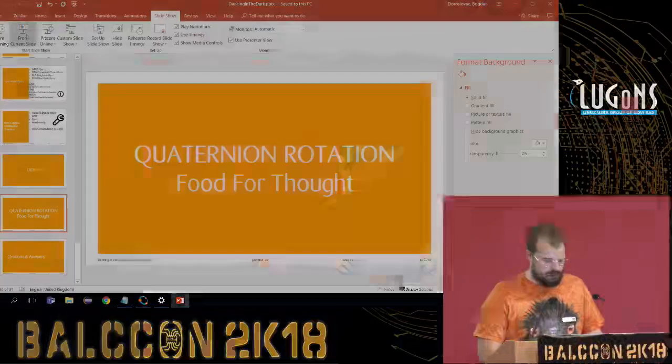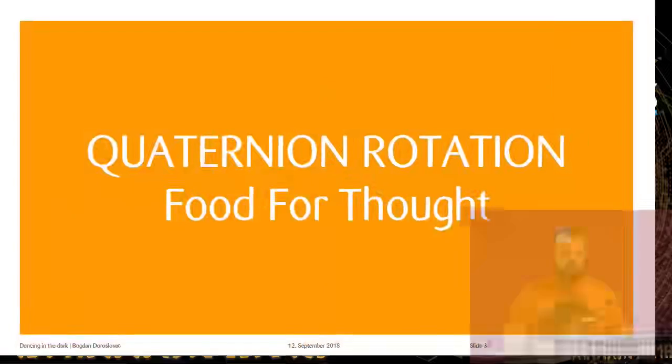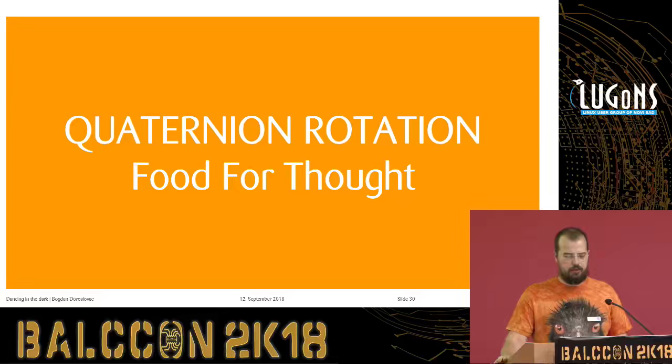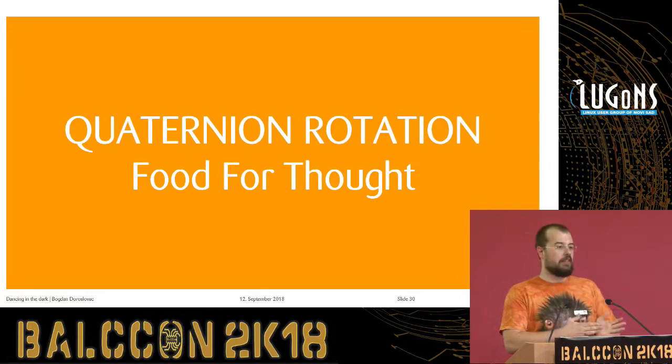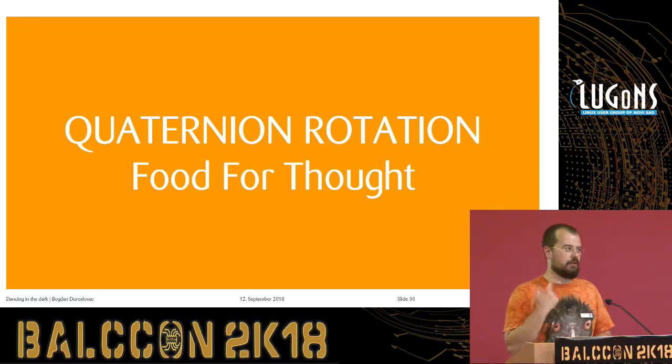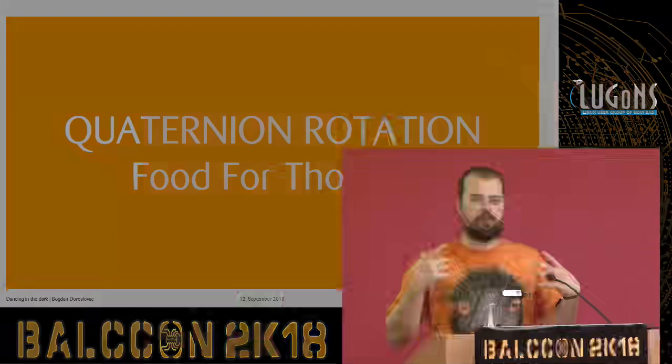One final thought is on quaternions. While redoing the lecture for the format, I decided to omit the quaternions as it would be too much math, but I just want to give you some food for thought on what it actually is. It's widely used in 3D graphics, and it's super awesome. Again, it has two approaches, navigation and 3D vector graphics. If we go back to how we position our platform in Euler angles, each rotation can be separated into three components: yaw, pitch, roll. What quaternions do is take the shortcut and find the one perfect rotation that gets your system into place.